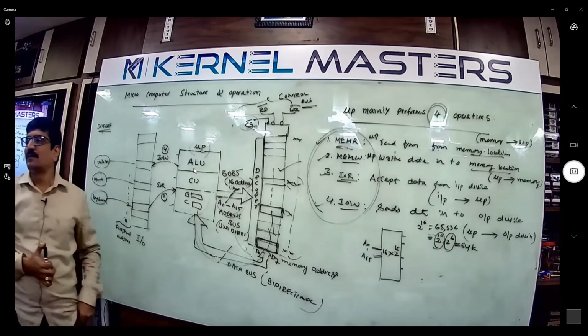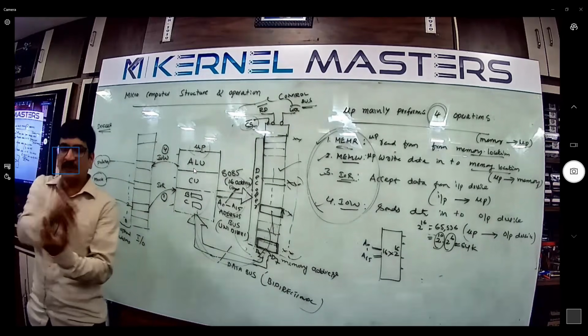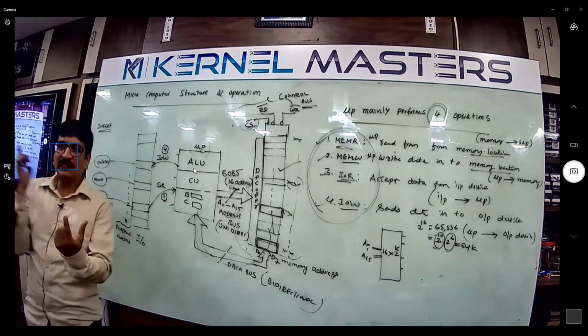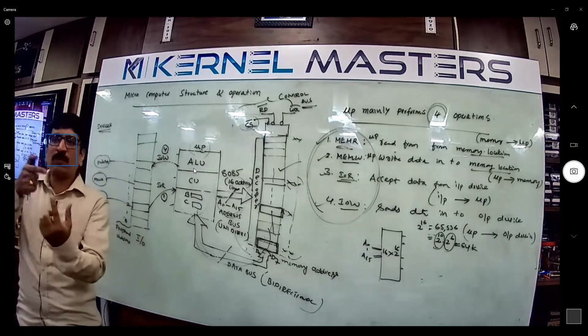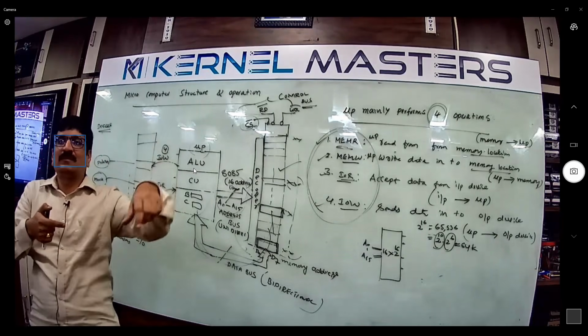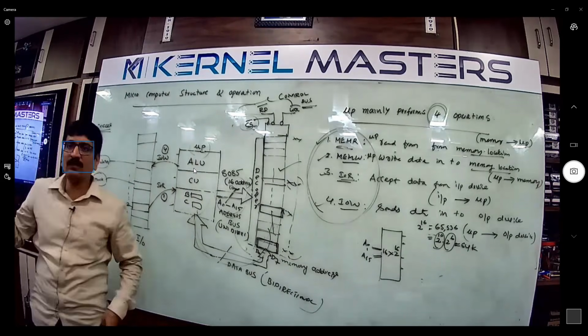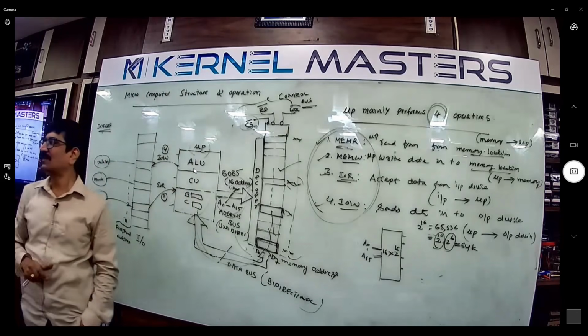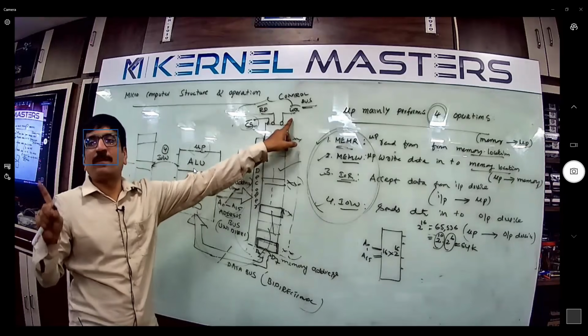You have an 8-bit register, and you are either writing or reading. The input of every D flip-flop has a tri-state buffer. When writing, write bar is low. When reading from the flip-flop, read bar is low. So the control lines are controlling. Whenever you perform a memory read operation, read bar is low.